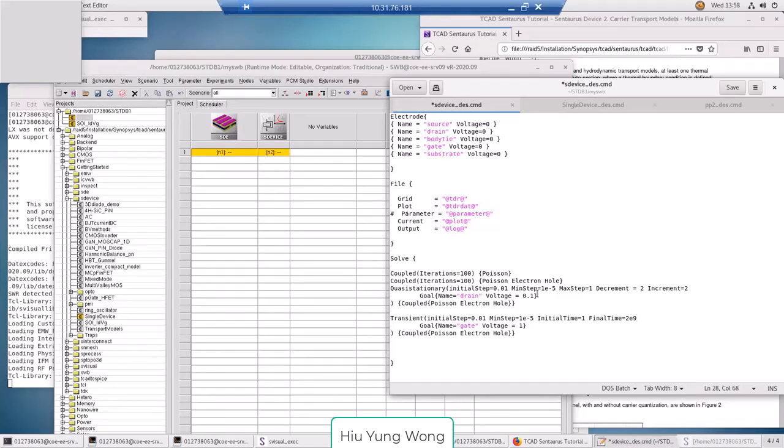Oh, okay. So the transient function is used when we're concerned about the starting stages, and the ramping rate, when time is important for us. Yeah. For example, in this case, we are not doing any memory, right? This device can do memory simulation. You inject electrons, then you need to use transient because you need to simulate for how many microseconds to see how the threshold voltage changes. You cannot use steady state. Okay, got it. Good.